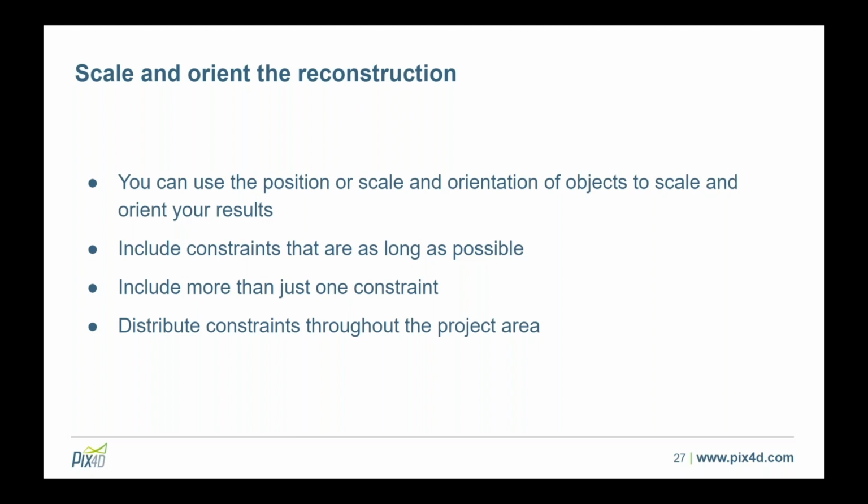Now, if you choose to include multiple constraints, please distribute them throughout the entire project area so that you can mark them in as wide a range of images as possible. Marking multiple constraints in a limited number of photos that are all clustered near each other doesn't have as much of an impact on ensuring that your reconstruction is correctly scaled and oriented compared to distributing the constraints throughout, because then you're able to mark the constraints in a greater number of photos.